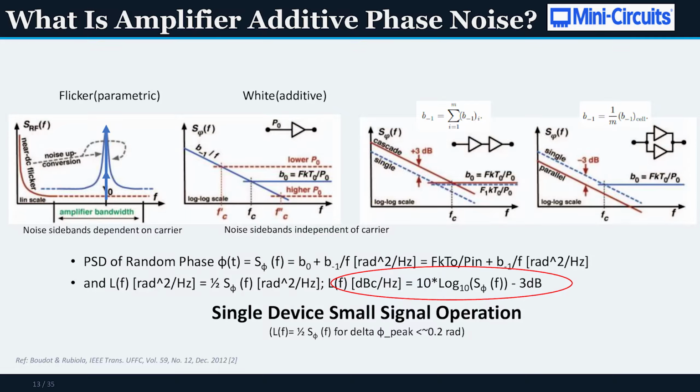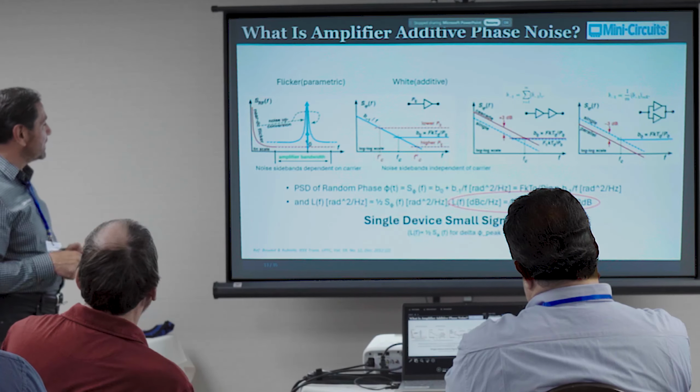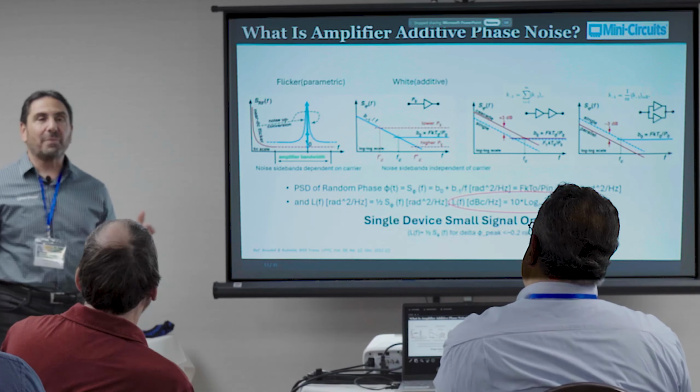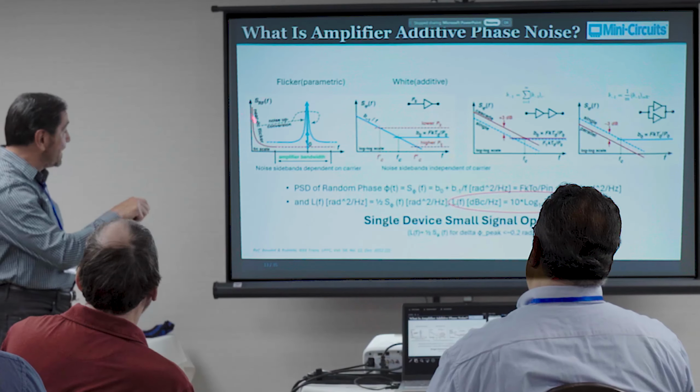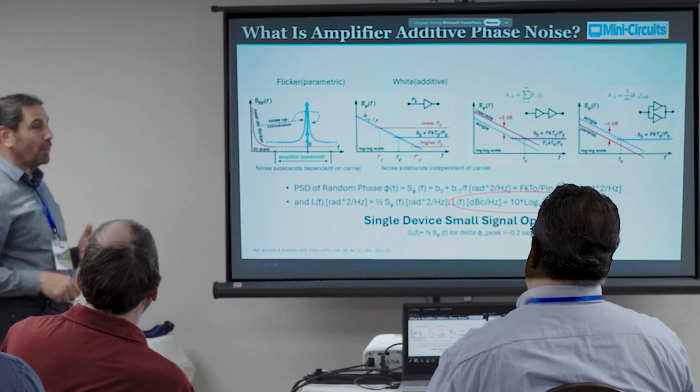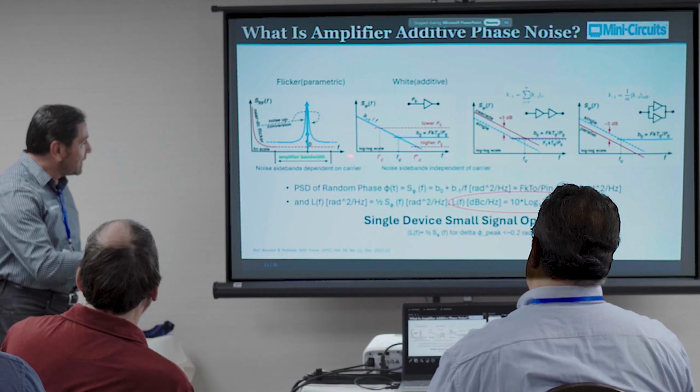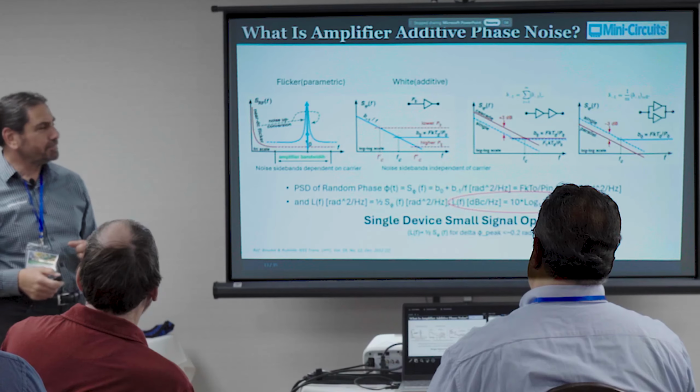But I just want to go through these quickly, because there's notation that us microwave types don't really use. We don't use S. So let's go through each of these in detail. This is power. This is your spectrum analyzer. This graph here is your spectrum analyzer. You're measuring power in dBm on the y-axis and frequency on a linear axis.